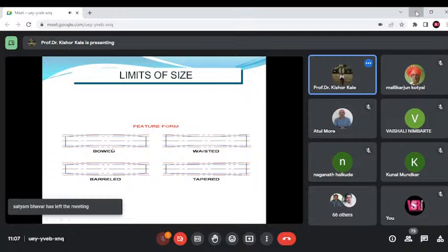Okay, now in GD&T there are some important symbols one should know. Maximum material condition, which we already covered, applies regardless of feature size. Least material condition we already discussed. Then there is the projected tolerance zone, the diameter symbol phi for a cylindrical tolerance zone or feature, and the basic or exact dimension, which will be given like this.